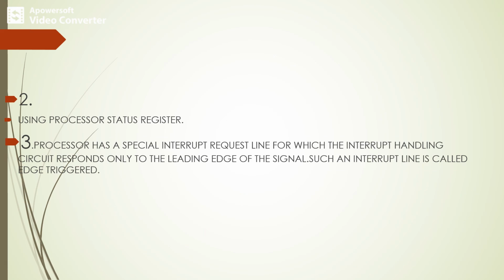So the second technique is using the processor status register. The second possibility is to have the processor automatically disable the interrupts before starting the execution of the ISR.